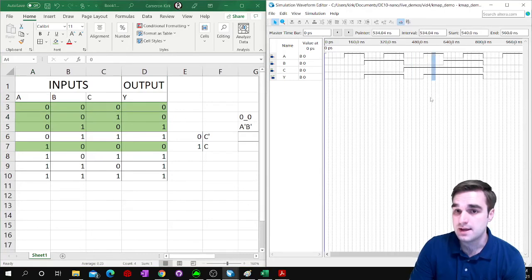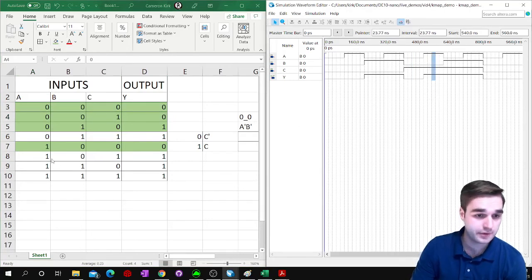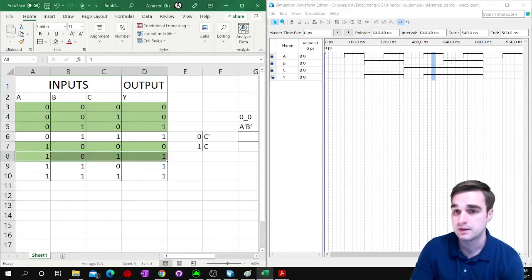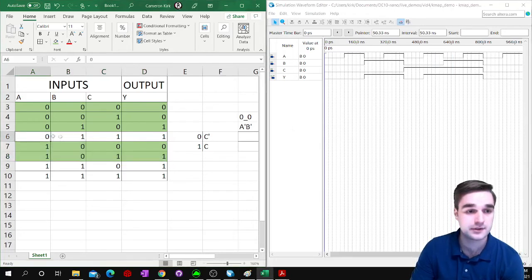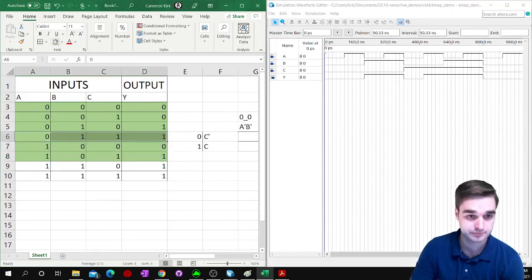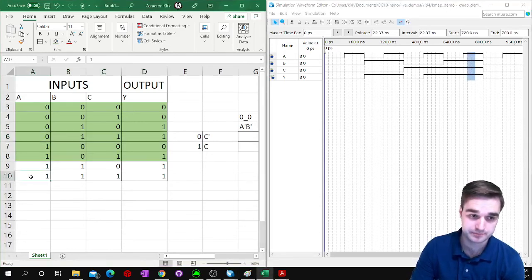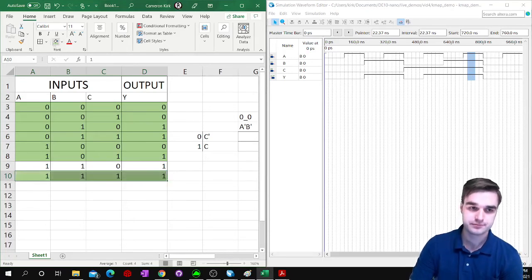Okay, when A is on, B is off, and C is on, that is our special case. That's this guy right here. We're looking good. When A is off, B is on, C is on, that is this guy. We're looking good. And when they're all on, our output's on. And again, this output, this is what I just decided were my requirements.